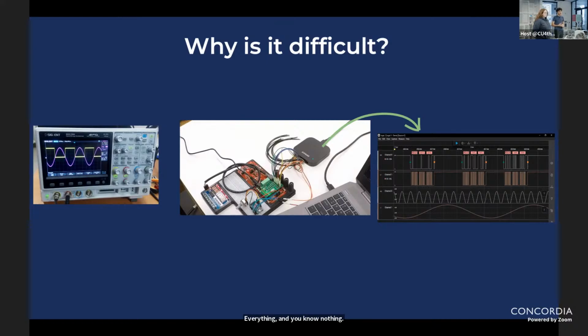And it's quite common to see unexpected behavior. To code something and expect it to do something, but then you get no response. And that's exactly when we debug. For example, we use the oscilloscope to check, maybe my serial communication device wasn't even sending a signal. That's why I'm not receiving any input. Stuff like that.